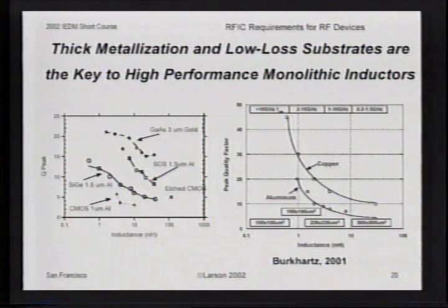The second thing that you can notice is that going to exotic substrates like silicon on sapphire or gallium arsenide gives you some improvements as well, because the losses in the substrate are essentially eliminated through an insulating substrate. One of the things that we see in silicon is that there has been an emphasis on increasing the substrate resistivity, using maybe float zone silicon or something else. And that might even boost us up a little bit further in the coming years as the resistivity of some of these substrates grows higher and higher. And once again, that's a very active area of research.